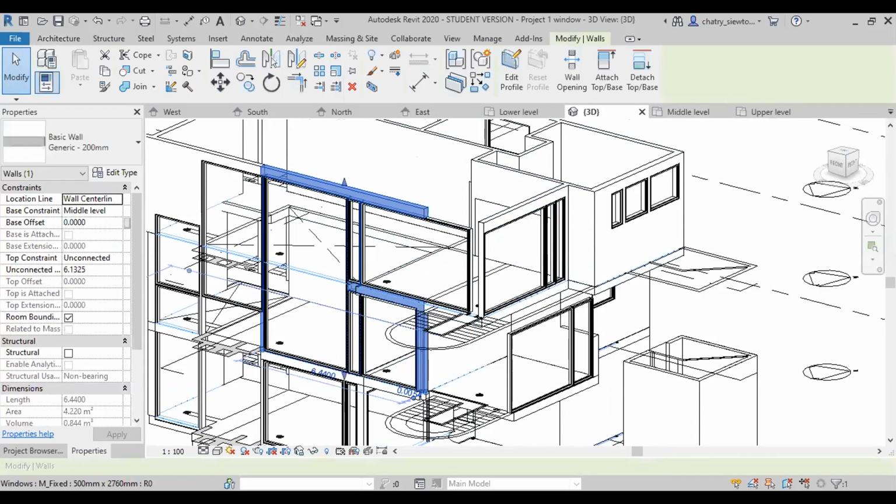You have to be careful here because first of all, what you are doing now is for the next class. It's not for now. Today you should just model the walls here. And as you can see, you have entered the very big windows. Here actually we wanted to use curtain walls. I think you are following the video in CN, right? Yes. It's okay, even if you did windows, but I would like to see curtain walls. It's not a big problem.